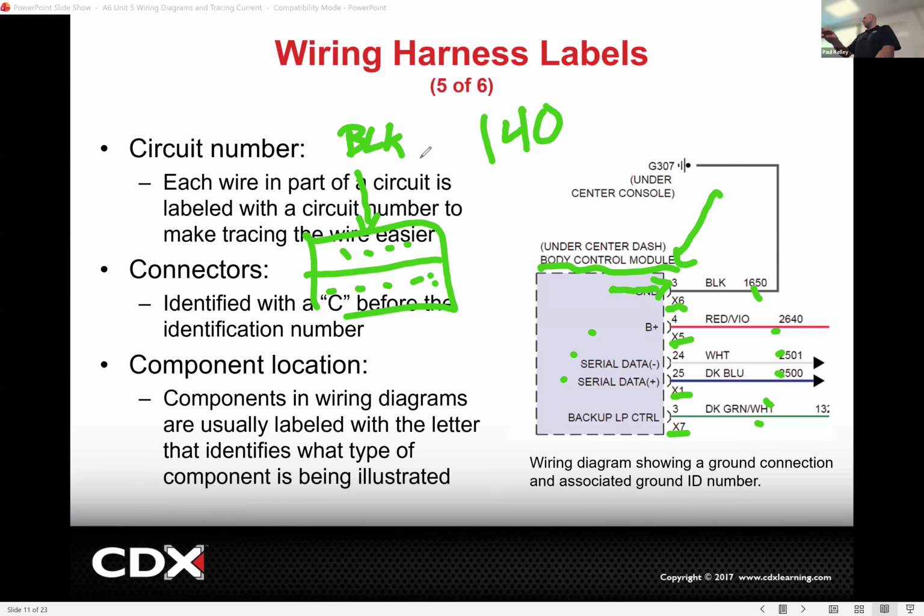He meant terminals. Some people would call them pins and I would call them terminals. So I'm a little more by the book. What he means by that is terminal number 3 is pin 3. So the whole time he knows, all right, to check the ground, I got to check pin 3, terminal 3. But he spends a lot of time trying to get the information for which connector it's in, where the connector is, the terminal number, and then making sure he's got the printout of the connector end view so he can find number 3. And so it was just funny. That was the thing that he brought up. He spends a lot of time looking for the right terminal.